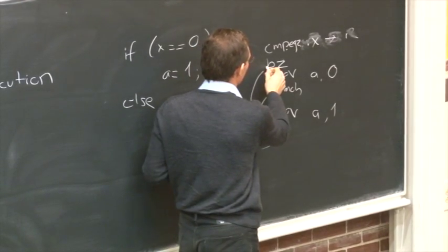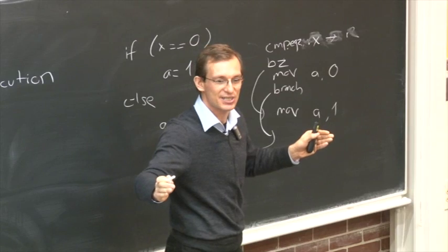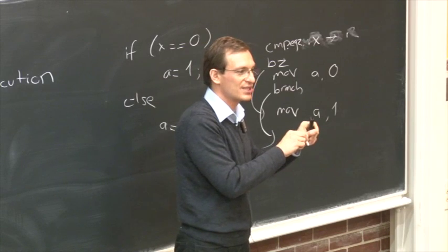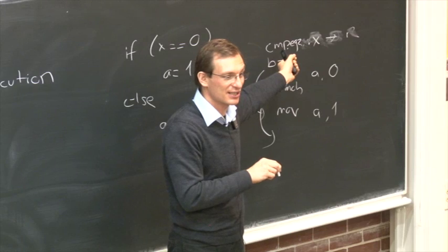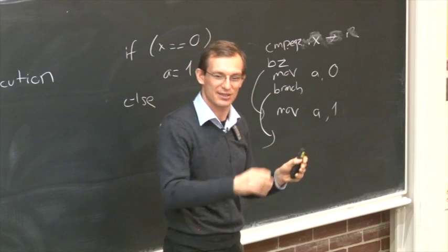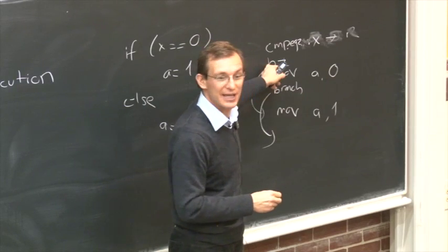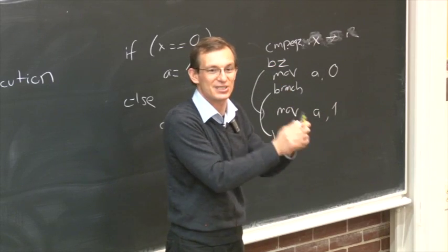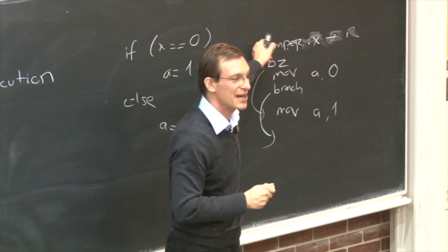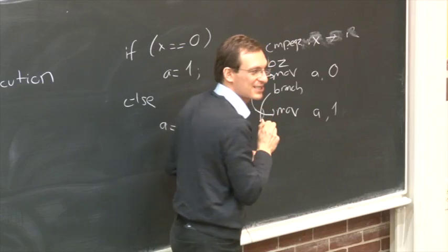If you're designing a pipelined processor, you're executing multiple instructions in different stages. And when you get to a branch in the fetch stage, you need to know what instruction comes next after that branch, right? You cannot move it to the decode stage, or even the execute stage, because you do not know what instruction to fetch until that branch is executed. The goal is to fetch the branch, decode it, and execute it, and these happen in different clock cycles, different stages. When you fetch the branch, you don't know what the next instruction is. It could be this, or it could be the target of the branch.